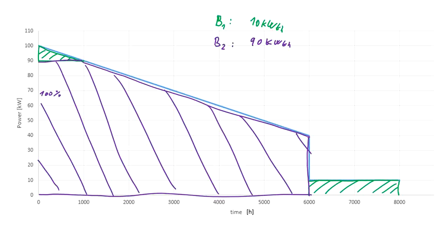And then the load is decreasing to 40 kilowatts out of 90, which is 44%, so perhaps it could have better overall efficiency. Here the 10 kilowatt boiler would be running at full power, so there the efficiency would also be good.